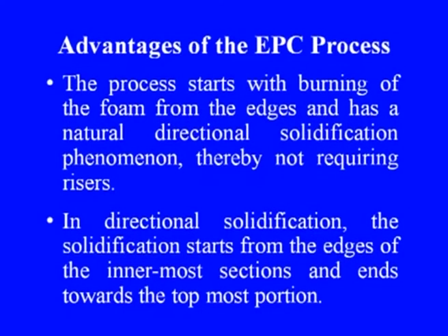The EPC process starts with burning of the foam from the edges and has a natural directional solidification phenomenon, thereby not requiring risers. In directional solidification, the solidification starts from the edges of the innermost sections and ends towards the topmost portion.